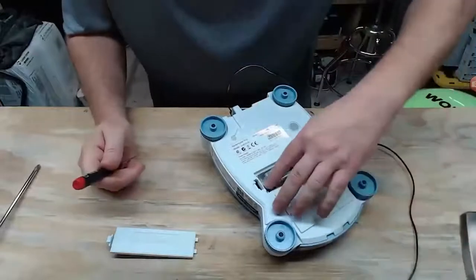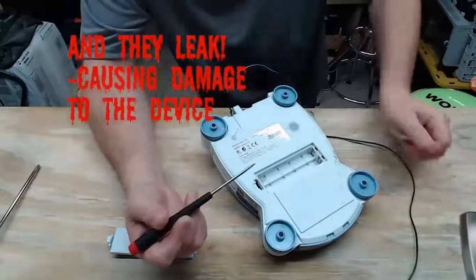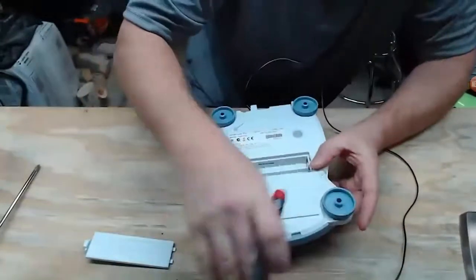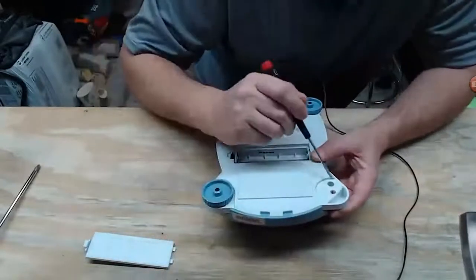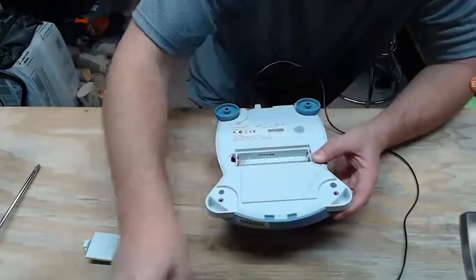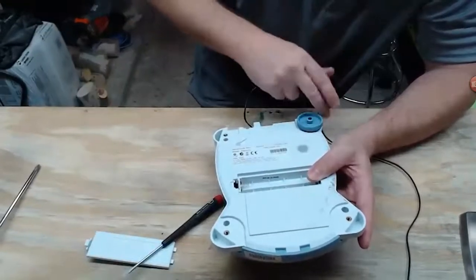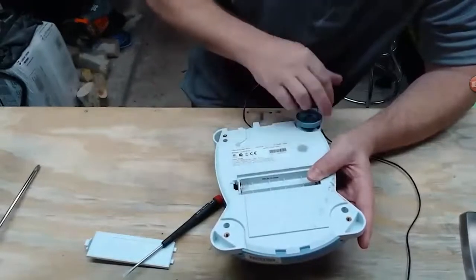The problem that we constantly have with scales is that users tend to leave the batteries in over a long period of time. And if you're running your scale off an AC adapter, there's no sense in having batteries in it at all. But here we are. You see how the leveling feet function? These ones here are hiding the fasteners which hold the whole scale together. One of the other common things we have to deal with is that users tend to lose or break the leveling feet. So if you're ever turning in a scale because something's broken on it, try and keep the feet. You'll need them later.